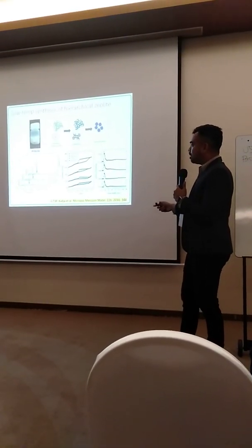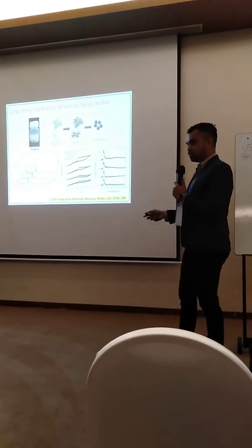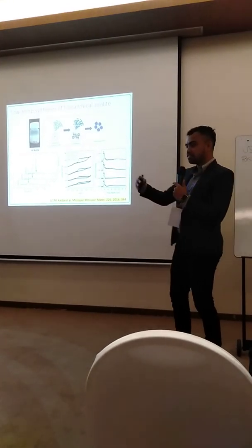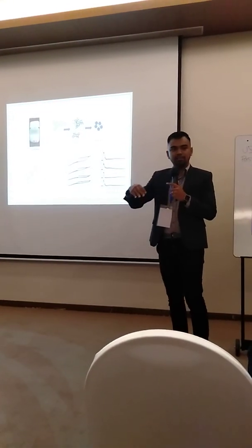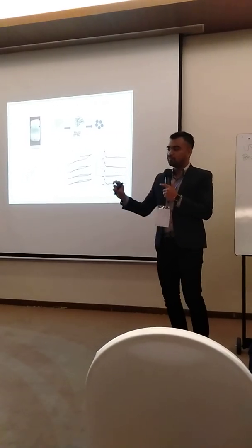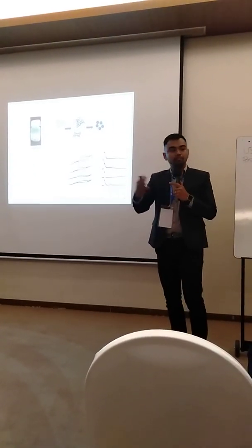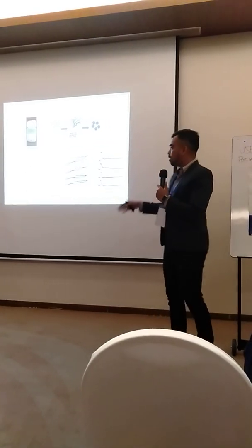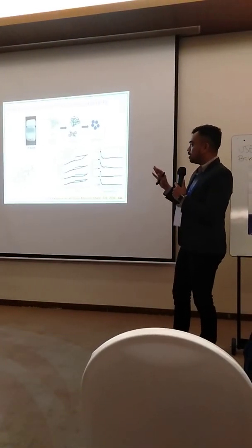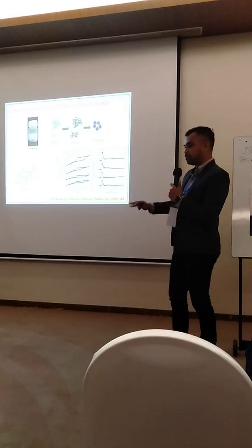If we reduce the temperature, the rate of crystallization will also decrease. But to overcome this, we lower the amount of water so that the concentration will increase, and it will compensate for the rate deceleration caused by the decrease of temperature.